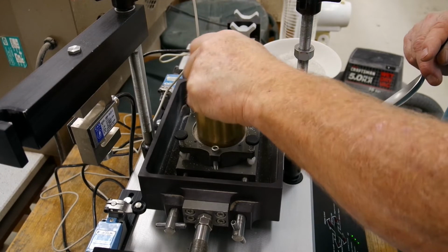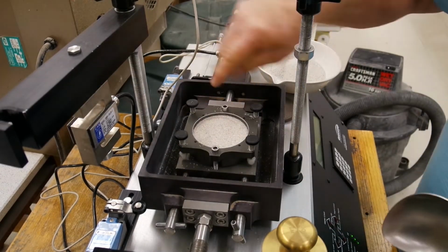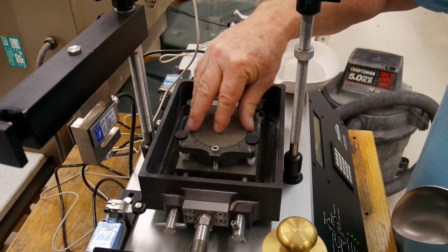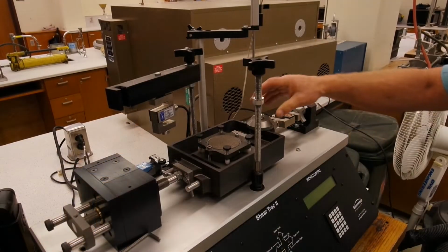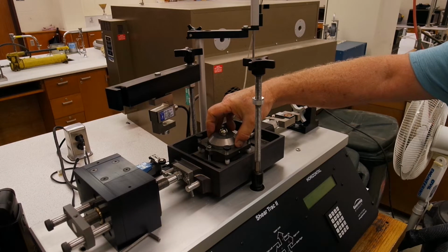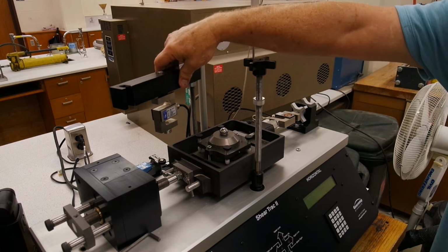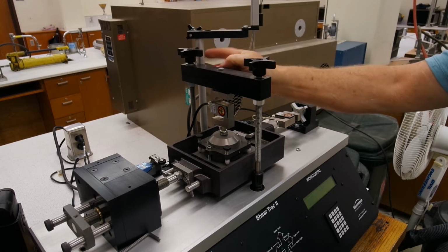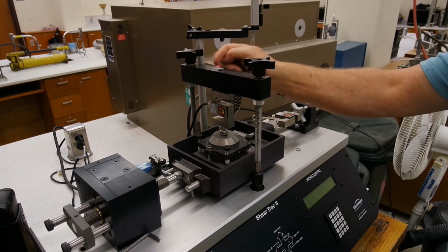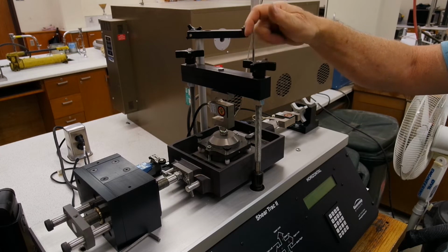Enough room will be left at the top of our setup to place our porous stone so that it is flush with the top of the setup. Then reweigh our sand and bowl to get the amount of material we placed into our setup. This will be the same weight we will use for all three tests so that our densities are the same.